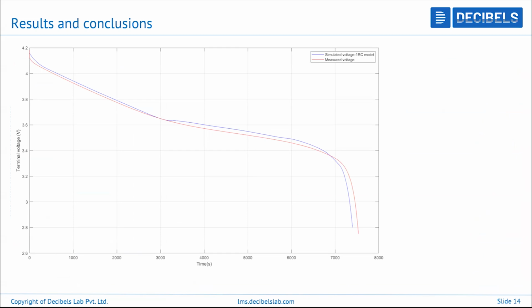As described before, we can model the entire electrochemical reaction utilizing the R and C approach. Then your ohmic resistance is already being represented there along with the capacitor, which talks about the change in your OCV with respect to the application of load. So that is one of the important conclusions we can make.